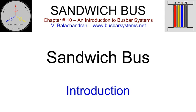Sandwich bus. It is also referred to as busways. Introduction. The synthesization of flexible and thin insulation material with good temperature withstand capability, Class B and above, led to the development of the sandwich bus. It has enabled low-voltage bus conductors to be pressed against each other with a thin insulating material between them, conducting heat across the insulation for efficient dissipation, and making the assembly extremely compact.